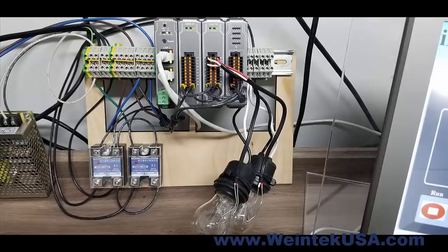This is the demo hardware setup. I've got an IR-ETH Ethernet coupler, an AM06-VI analog I/O module, an AI04TR thermal input module, and an 8-in, 8-out digital I/O module with source output. I have two AC incandescent light bulbs with a thermocouple connected. I have the AC current isolated from the digital output with solid state relays.